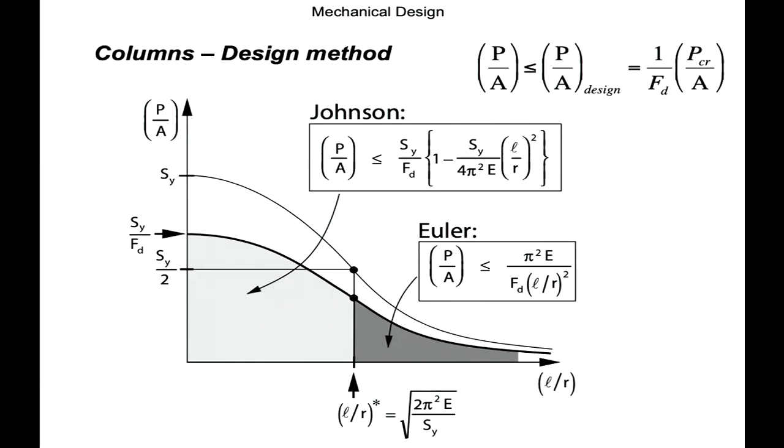Recognising that even with what I've got up there, yield strength, and you've got yield strength divided by a factor. I can tell you it's not 2, it's probably about a design factor of safety of about 1.5, I'd imagine, something of that ilk. A design factor of safety of 2 would bring us down to this halfway point, and then we'd have another curve going along there.